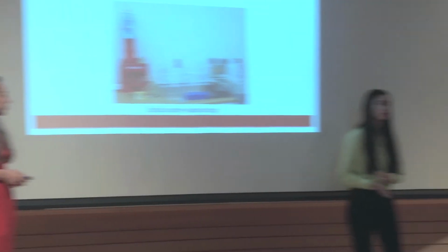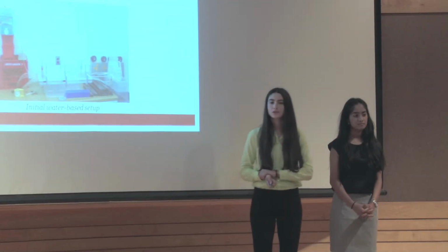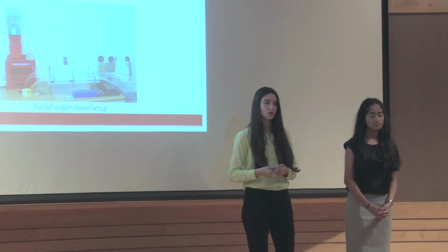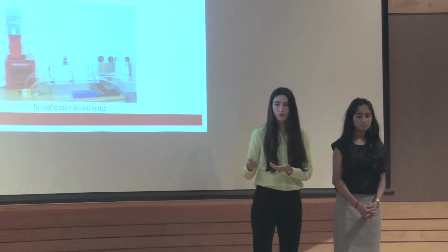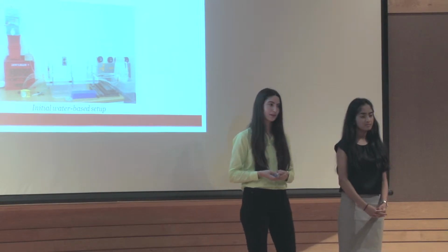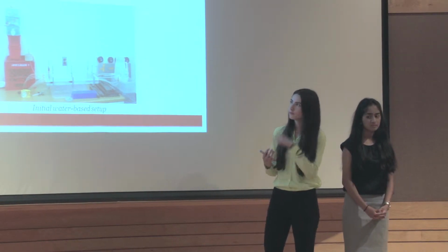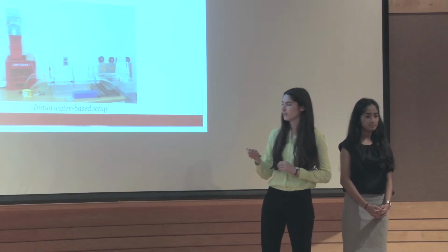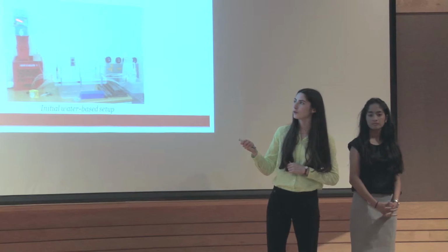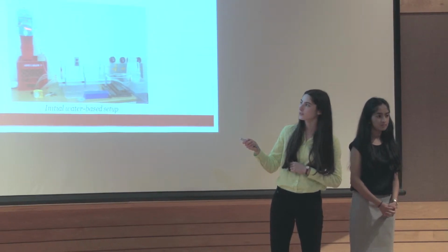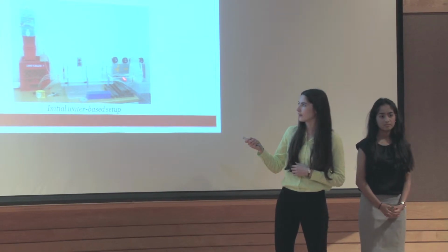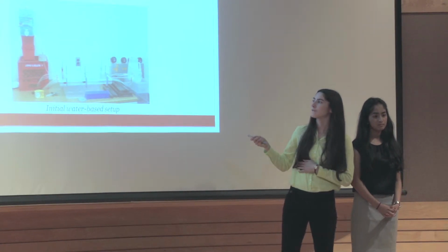So once we conducted our 3 gravity-based trials and concluded that setups 1 and 2 were the most effective, we decided to translate it into using a flow of water as the driving force rather than gravity, because it would better simulate what happens in a microfluidic environment. So for our 4th setup, we had the setup in a shallow tank here, and the flow of water came from a water jug that was placed above it, so it would create a higher flow, and then it would continue out through tubes to this dispenser here.